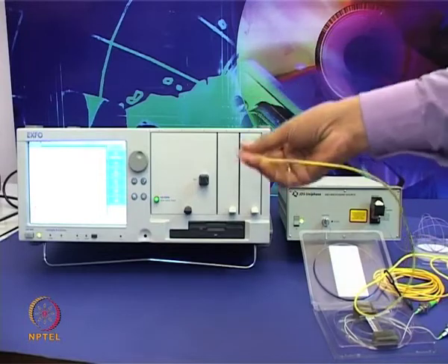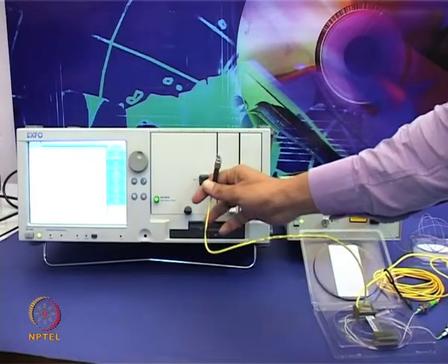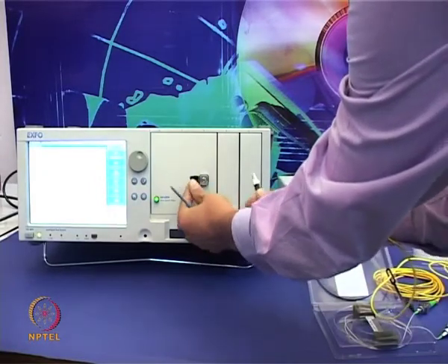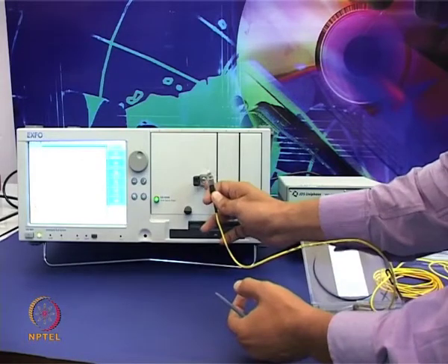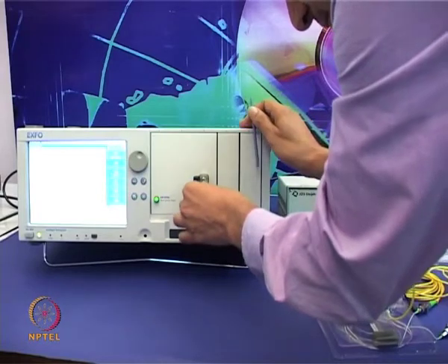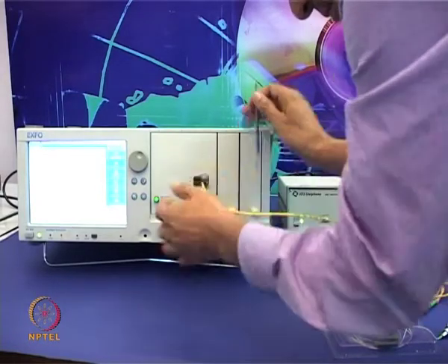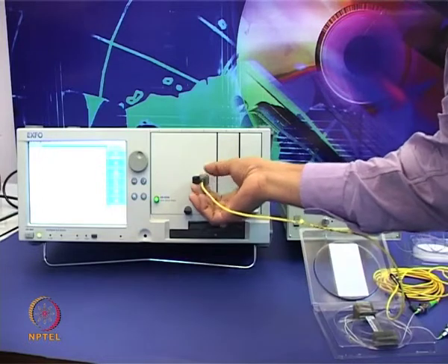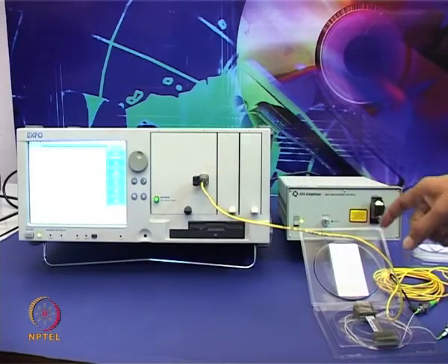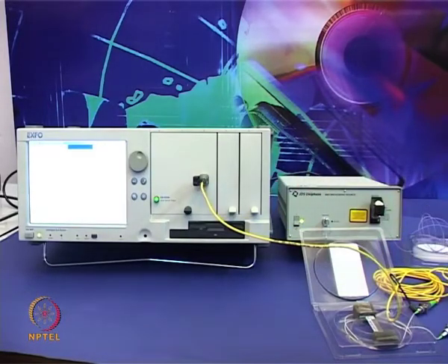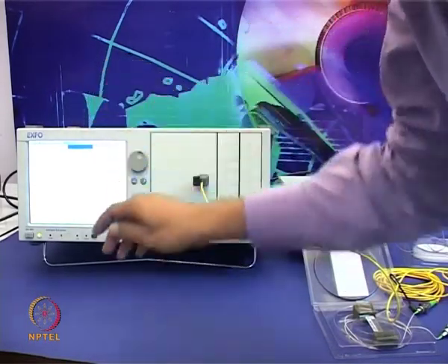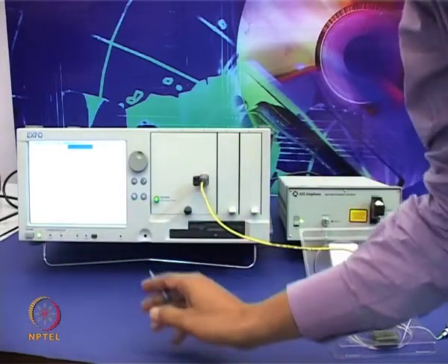Optical patch cord is being connected to input of the spectrum analyzer. Patch cord consists of a notch which has to be matched with the input, which will be demonstrated clearly in the latter part. Has to be twisted properly till it properly gets fixed to the input. The green light on the screen shows the initialization of a spectrum analyzer.